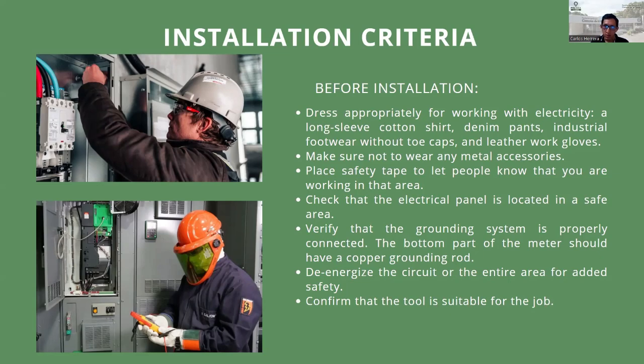Check that the electrical panel is located in a safe area. Verify that the grounding system is properly connected, and the bottom part of the meter should have a copper grounding rod. De-energize the circuit for the entire area for safety. Confirm that the tool is suitable for the job. Next,